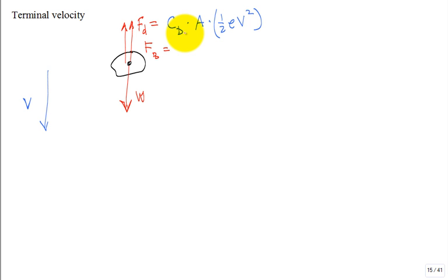How can I write an equation for the weight of the fluid displaced? It would be equal to m times g. What is m? The mass of the fluid that was displaced. Well, the mass of the fluid displaced would be the density of the fluid times the volume that's displaced. Let's distinguish that V from the other V by saying, hey, this is the volume V. True?